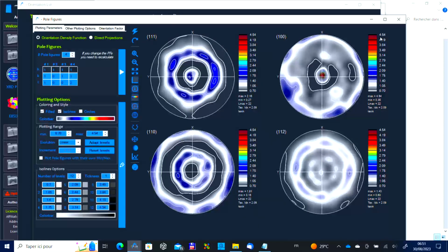The 4.5 means that it would be 1 if the distribution is random, isotropic. So 4.5 means that many times not isotropic with respect to the isotropic one. It's a relatively not too high value, but not too low either. We see these concentrated circles. So we have a texture actually, probably the sample was a bar.